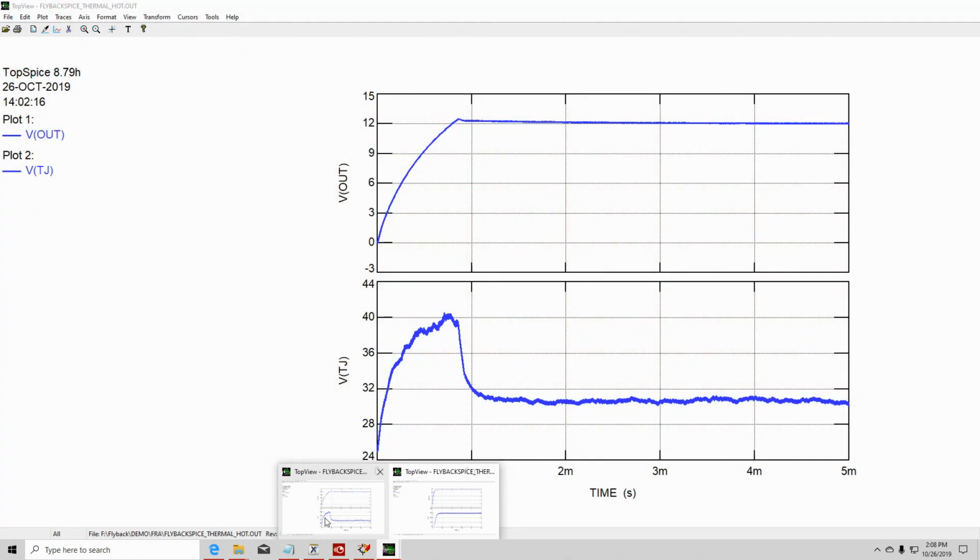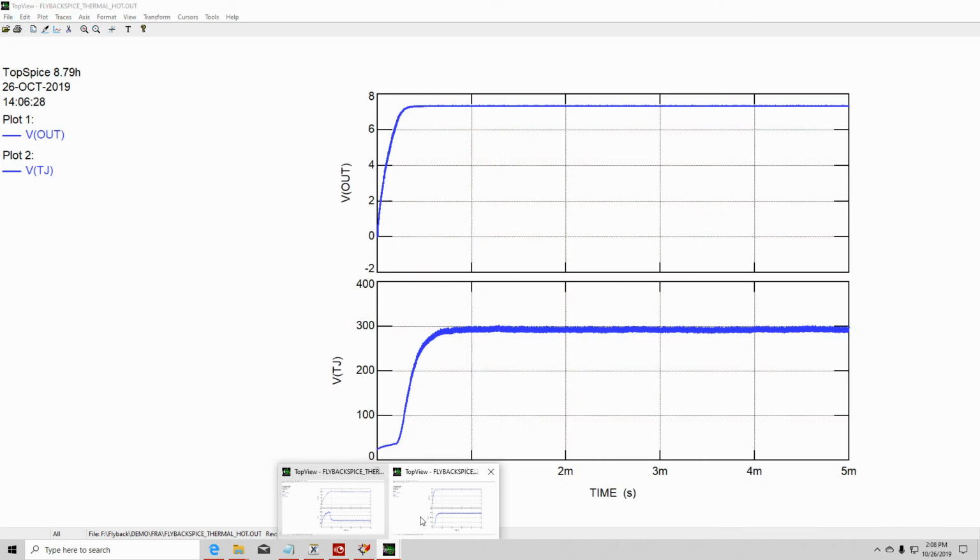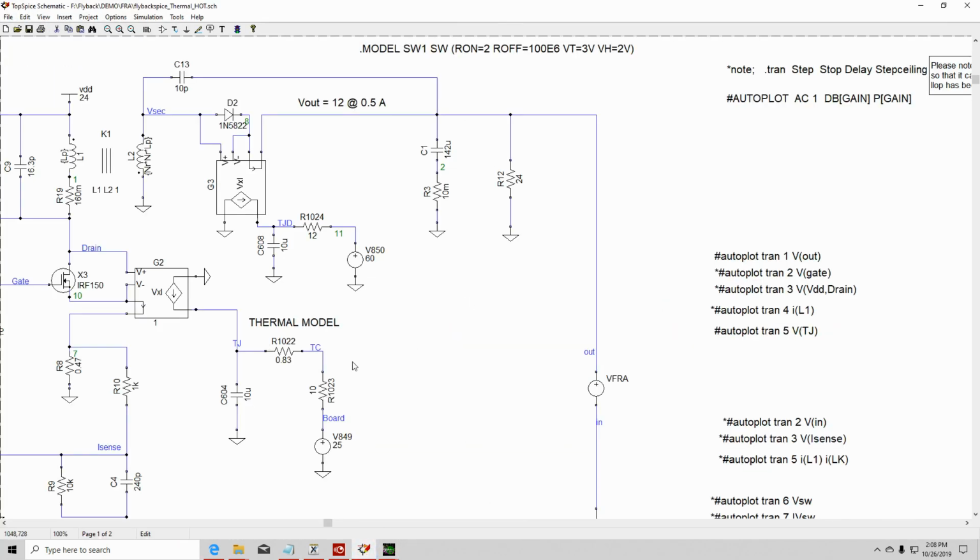And if you notice, the voltage doesn't even go up to 12 volts, because the voltage at the drain is being clamped at 100. And remember, when you decrease the turns ratio to 0.1, the drain wants to go to 150 volts, but because the clamp is 100 volts, it doesn't allow the output voltage to go up. So that's a big, powerful tool to have in your tool chest, learning how to do that.